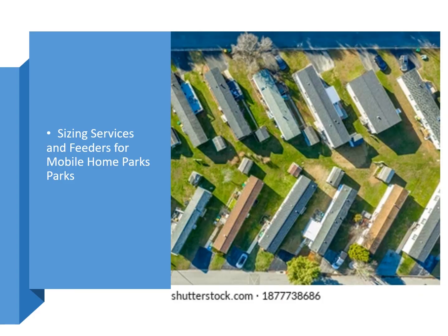When it comes to sizing mobile home park services and feeders, we look at Rule 72-102 Subrule 1, which tells us that for our individual motorhome sites, we're going to use Rule 8-200, so we treat them as a house. When it comes to looking at our entire mobile home park, we look at that as an apartment building. Therefore, we're going to use Rule 8-202 in order to size the service for the entire mobile home park. This would also include any other buildings such as bars and pubs and common areas. We'd have to take those into account according to Rule 8-202.